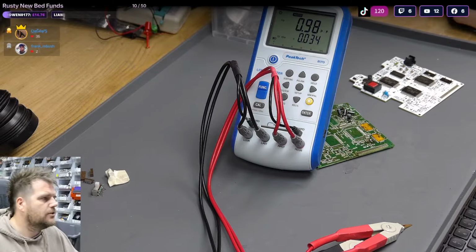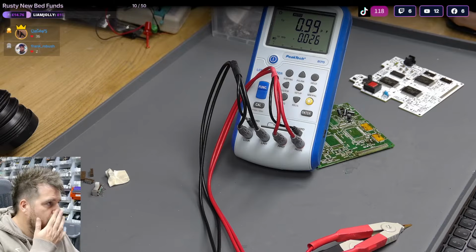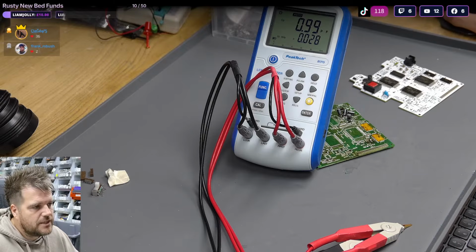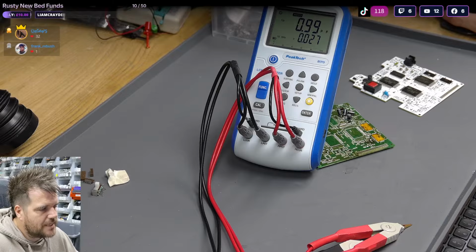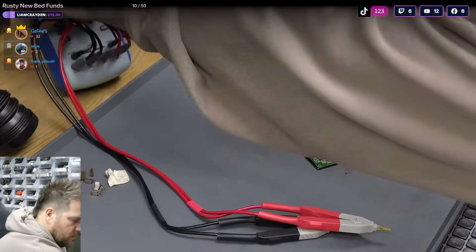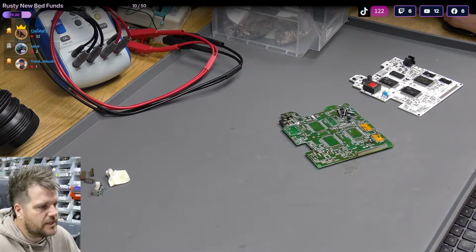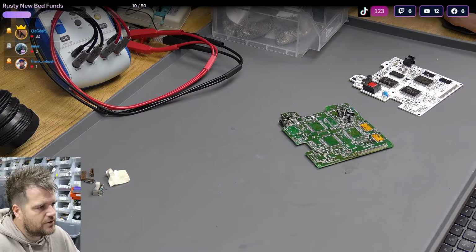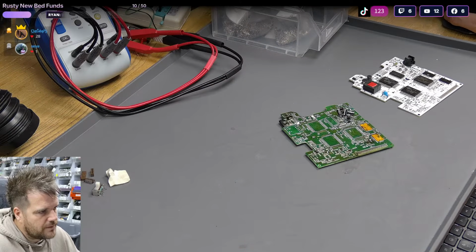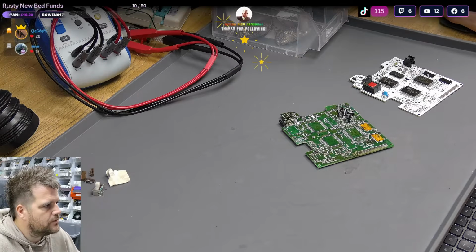Slightly non-standard. Let's see if maybe the PC Engine's schematic, the desktop version of this, has any caps that are in a similar range and in a similar area, just to give us a bit more feedback on that so we can make the right choice. If not, the reading will be accurate enough. It won't be a problem.